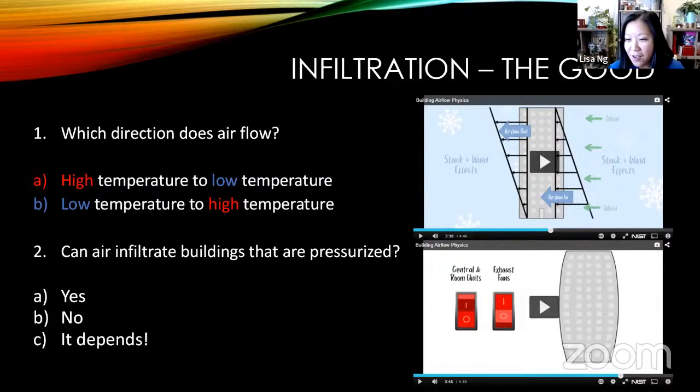All right, so I think we have a mix of answers here. And if my answers are wrong, I am sorry they are wrong. This is just how my brain works. All right, so Matthew says the first one is A, and then number 2, the answer is C. So I think a lot of you got the answer to number 2 correct, which is yes, buildings that are pressurized can still have infiltration, but the answer is also C, it depends, because it depends on the weather outside, what's happening in the building, as well as where in the building there is pressurization. It is oftentimes hard to pressurize an entire building unless you are doing a building pressurization test.